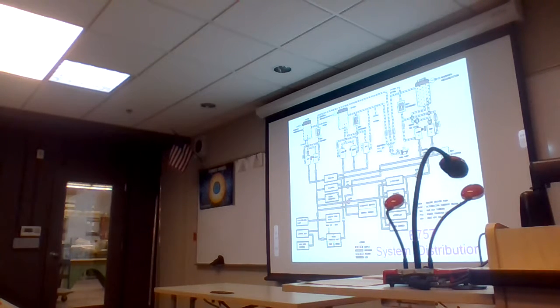But if, say, for example, the left system has lost its pressure, what we can then do is introduce fluid into the motor side of the PTU. It uses hydraulic fluid from, I have to trace this back, but it looks like from the right system, in order to repressurize the system by operating the pump on the left side. So there's no direct transfer of hydraulic fluid. After all, if you've lost the fluid from the left side, this is your opportunity to attempt to repressurize the circuit using existing fluid. And it usually picks up fluid from below the standpipe level, the very bottom of the reservoir that's held in reserve. So it's good for a limited period of time.